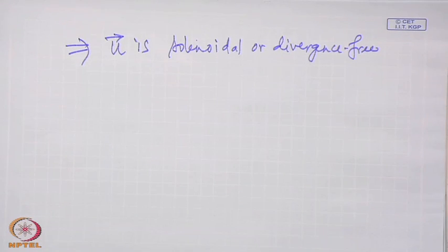So, you see that incompressible flow imposes a certain restriction on the velocity field. Any field, which is basically just a mathematical function of spatial position and time, that you can choose cannot be a possible candidate for the velocity field.